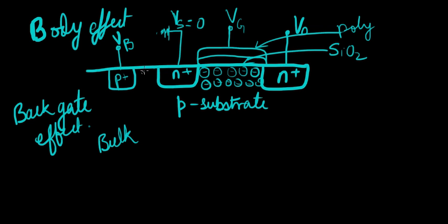Generally, because we know that even this has to be reverse biased, for a P plus region, reverse bias would be to connect it to the most negative supply in the system. And you have, say, 0 to 3 volts. So the most negative is 0 volts. That means, along with the source, even this is considered to be grounded. So in short, the source and the body, or the bulk, need to be at the same voltage.